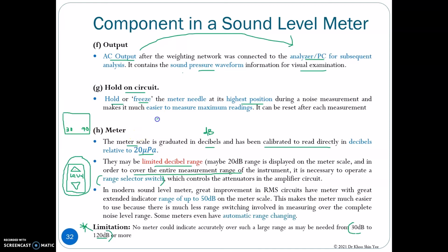If you want to measure the sound at 80 dB, then if you press the top button here once, the number here will change to 40 to 80. And if you press once again, then it will change to 50 to 90. By doing that, now the range is suitable for the target.